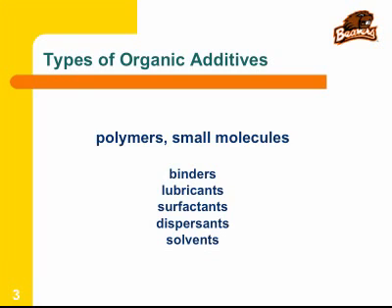Yes, so just what is called bulk density in common parlance. If you didn't apply any agitation, what is the packing characteristic of the powder? So what is another type of density? This is what we are referring to as a compaction density, right? Compacted density. You apply pressure and you can push the powders closer together.